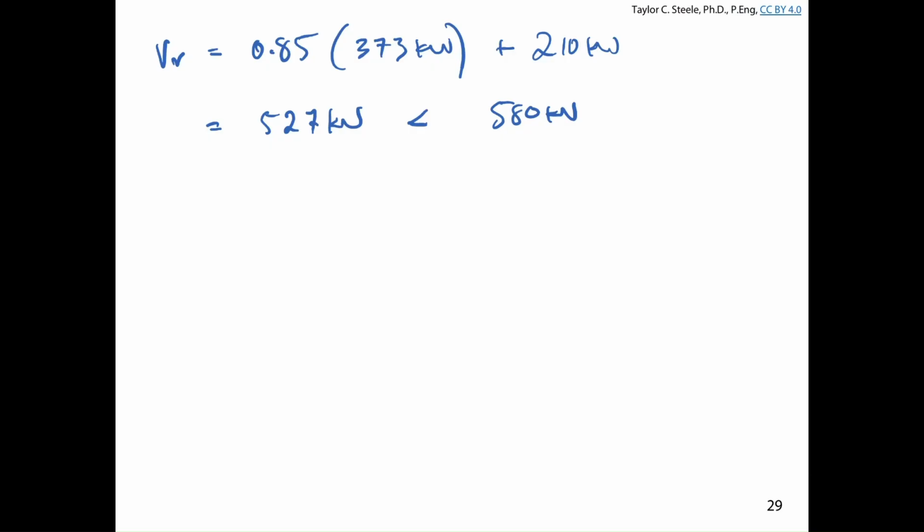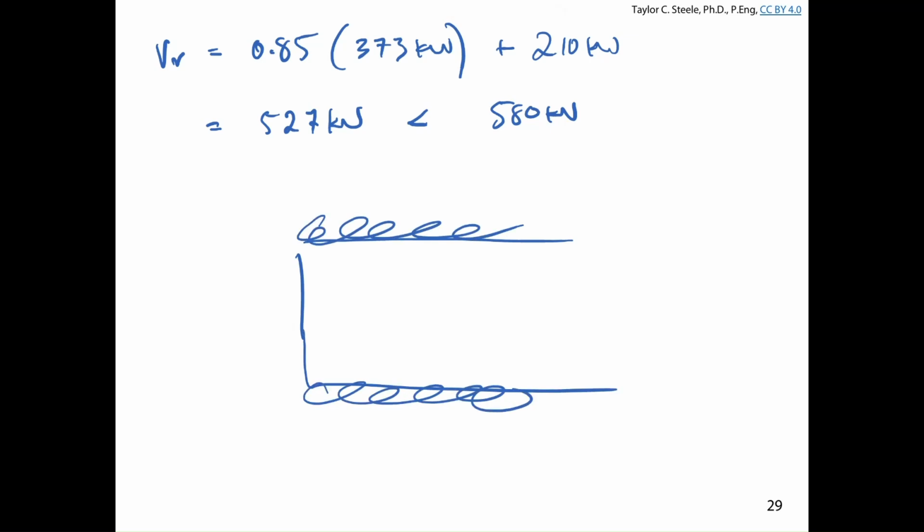So thankfully, that's not the actual detail in that building. I made that one up. And the actual detail is something more like this. They actually have 8 at 250 on both sides, okay? So the real detail is two welds loaded in direct shear, and so we've got 8 millimeters here, 8 millimeters here, and 250 millimeters worth of weld length on either side.